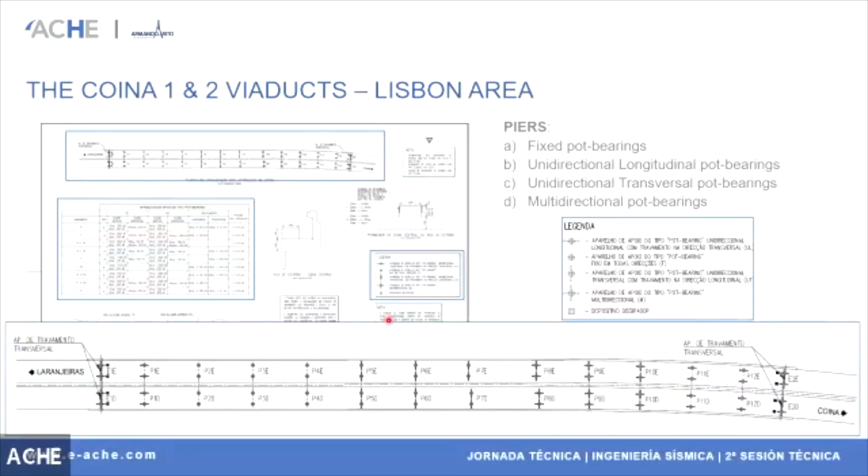On the piers, I don't know if you can see it here, but we had a zone with quite severe liquefaction problems, so the displacements in the transversal direction were bigger, so we had to free the bearings in the transversal direction and also in the longitudinal direction, because we also have the displacements from creep and shrinkage and temperatures. So we freed transversally the bearings here. We had only these two alignments fixed transversally because we had this fixed point here on the abutment and also here. So we defined the position of the bearings, or what you free for the bearings, depending on the soil conditions, the height of the piers, and so on, with simple and conventional solutions.